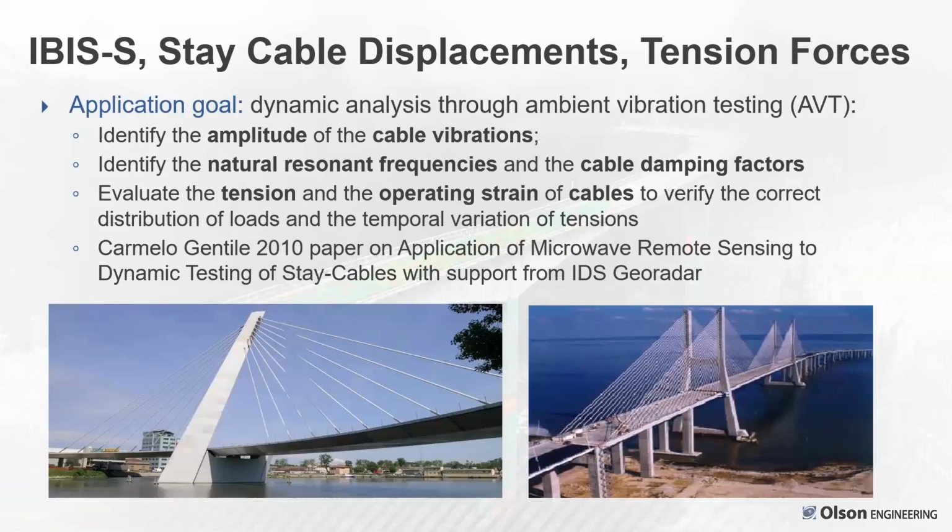We also want to discuss another application for the IBIS-S, which is to monitor the vibration of stay cables or stay cable bridges. The goals of the monitoring would be to identify the amplitude of the cable vibrations, to identify the natural resonant frequencies and potentially damping factors, and also to evaluate potentially the tension and operating strain of those cables.